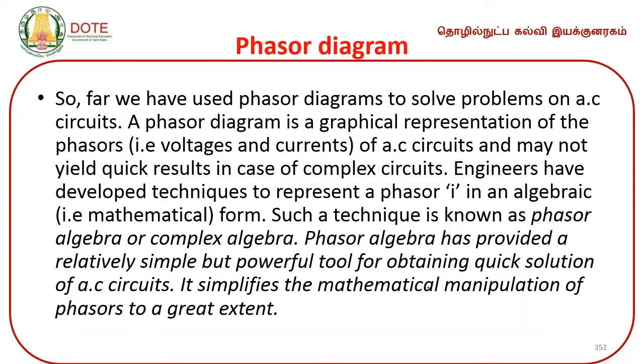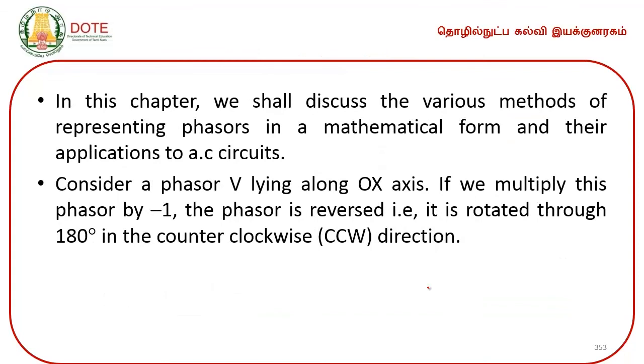So far we have used phasor diagrams to solve the problems on AC circuits. A phasor diagram is a graphical representation of the phasors of AC circuits and may not yield quick results in case of complex circuits. Engineers have developed techniques to represent a phasor in an algebraic form. Such a technique is known as phasor algebra or complex algebra. Phasor algebra has provided a relatively simple but powerful tool for obtaining quick solutions of AC circuits. It simplifies the mathematical manipulation of phasors to a greater extent.